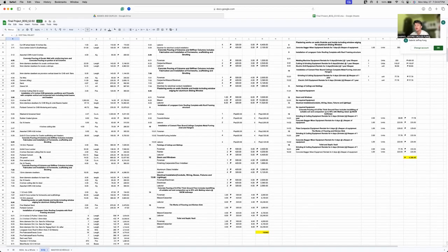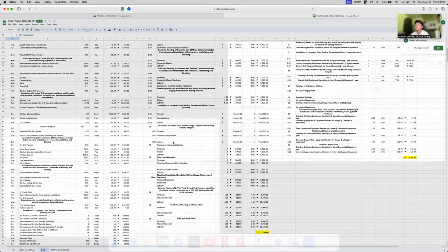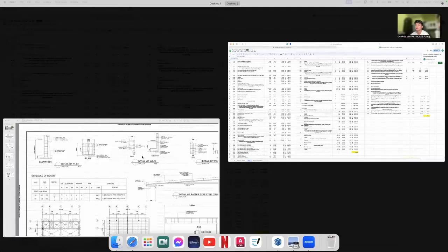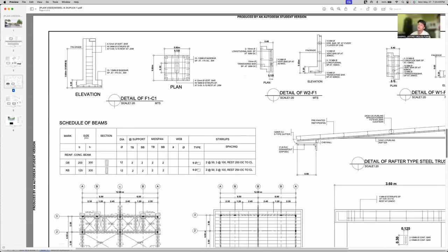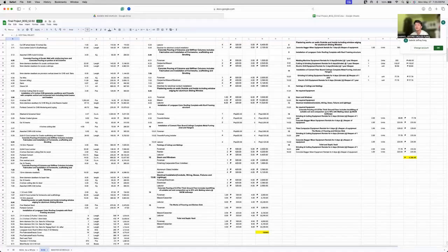identify the number of Portland bags needed, because first and foremost, we had acquired the volume of the footing with the given dimensions, and then we divided it by a class A Portland cement with specific ratios. It goes the same with the 3/4 gravel as well as the fine wash sand. So with this in mind, I assume that the entire footing is approximately 14 cubic meters.